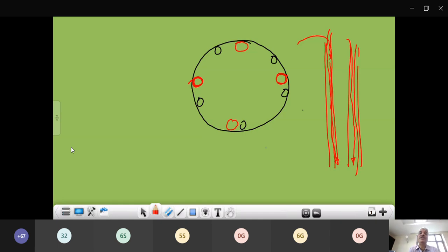Normally you use 2 tubes at a time, this and this, and then you do in this and this. So these ultrasonic sensors are lowered in this, and this one is the receiver, another is the transmitter. This transmits an ultrasonic signal which this will receive, and something will reflect back and come, and then you pull them out at a constant velocity. So both of them are here, next time they are here, then they are here, and these signals are recorded in a processor, in an equipment, and then it is processed.